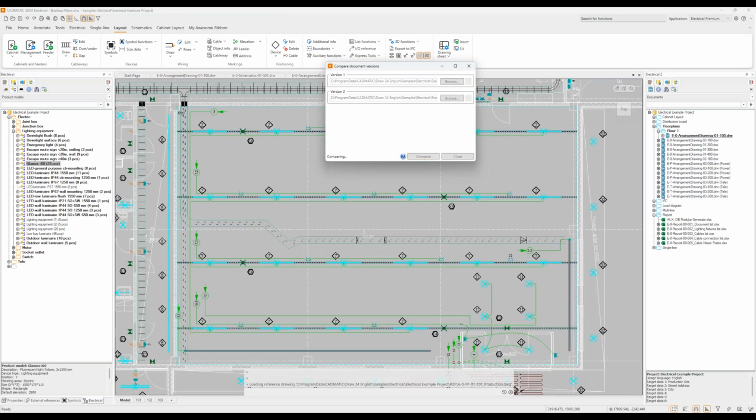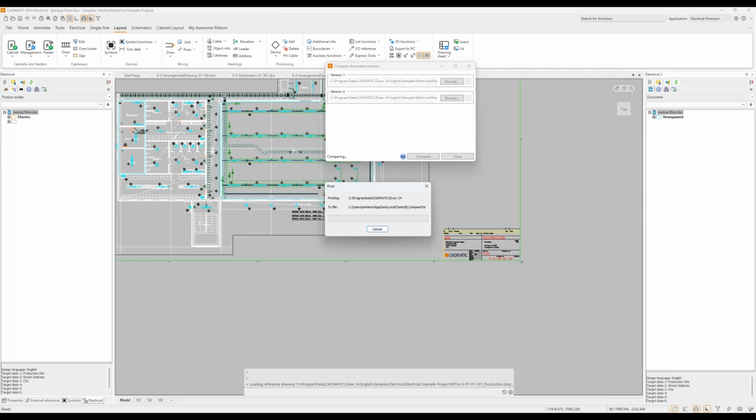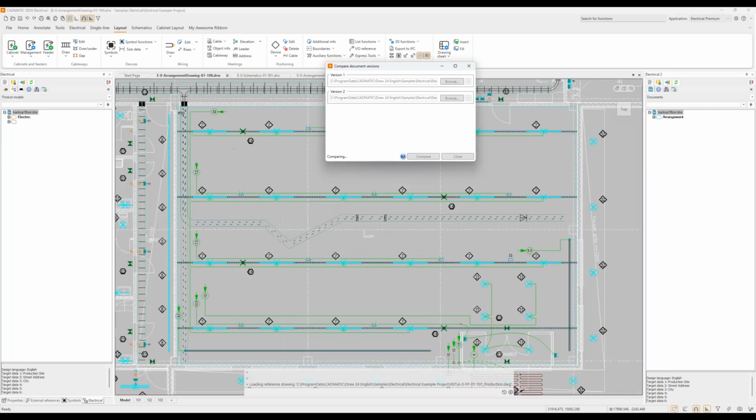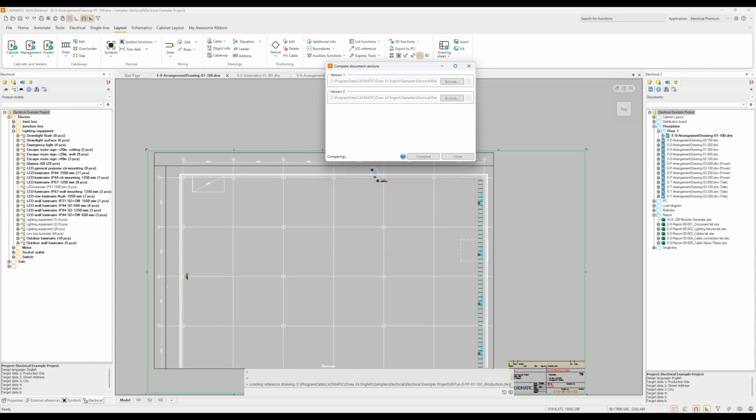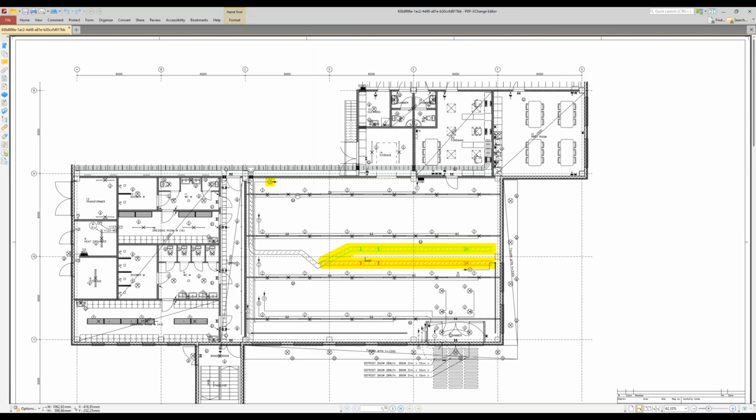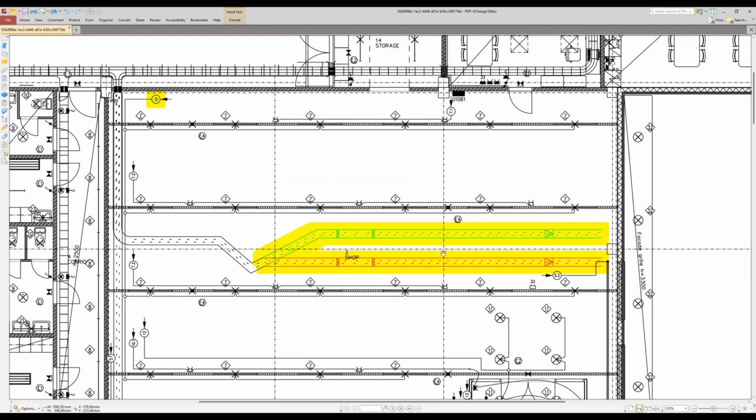And what is it actually doing now? It's just creating two PDF files and comparing them on top of each other. And it's comparing the pixels on those. And when it finds a difference, it will highlight that one in yellow. When it finds a new one, referring to the backup version, it will create that one as a green, and the old or deleted one, well, you guess, it will be in red. So I made the change. I deleted this, not to delete, I moved it to be here. So each change, and here as well, the group number has changed.